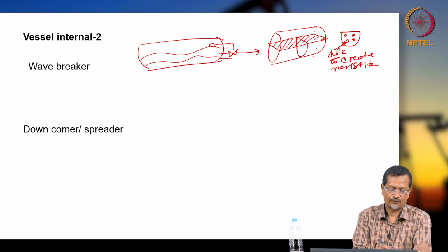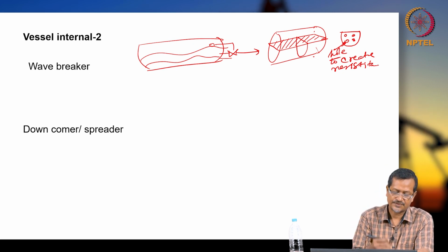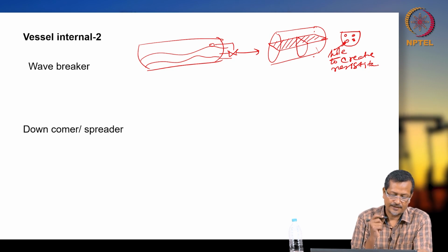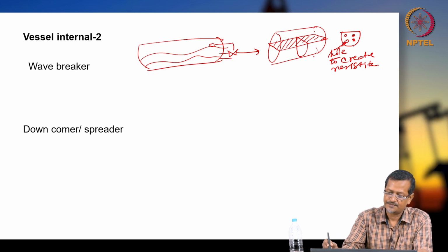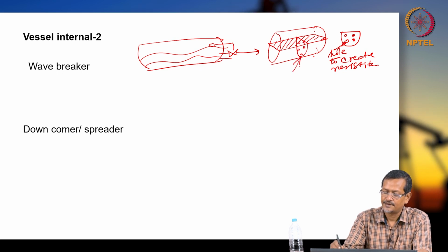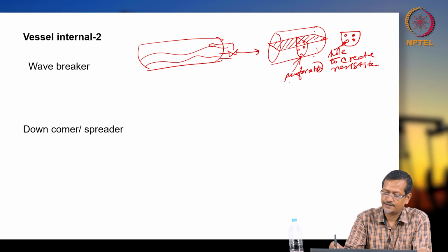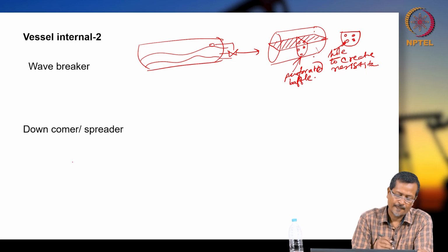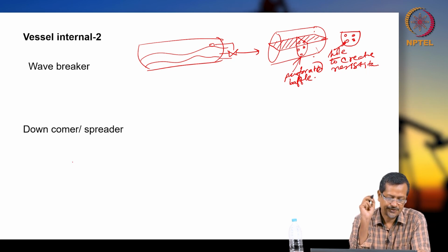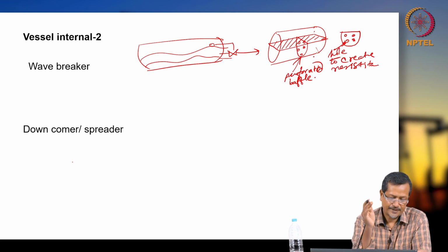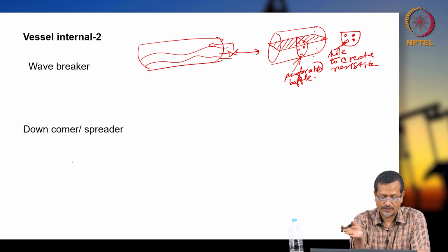Wave may result from surge of liquid entering the vessel. Nothing but perforated baffle. This is called perforated baffle plate, placed perpendicular to the flow. Wave action should be eliminated, then level control will work.